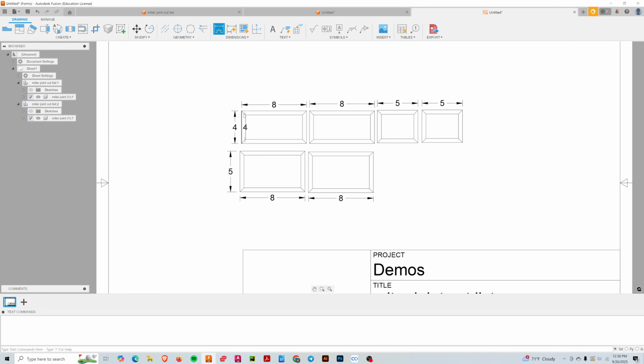And then I'm going to do it really quickly from all the way over here, this end, and vice versa. So remember that each cut that you do is going to take off 1/8 of an inch because that's the thickness of the blade. So just to be safe, I will buy a piece of MDF that is 30 inches by 12 inches to make our cuts.